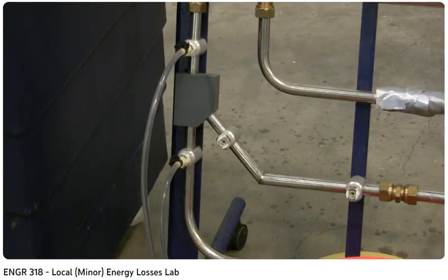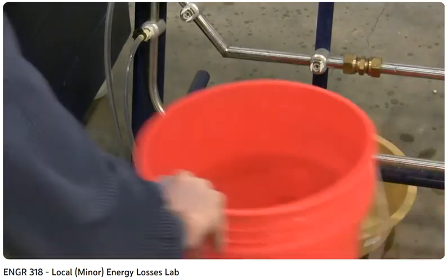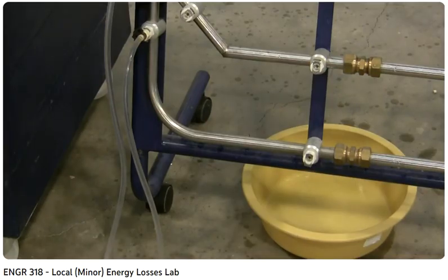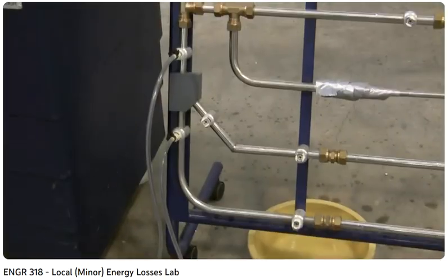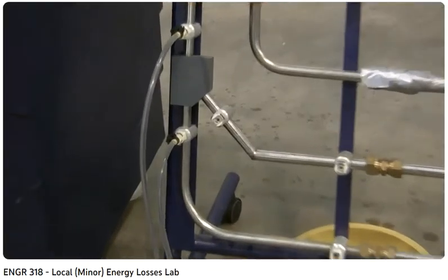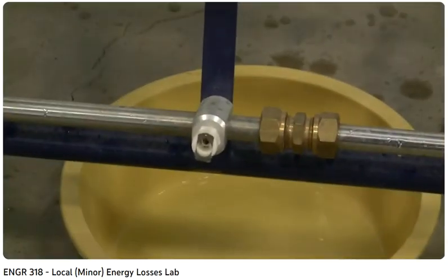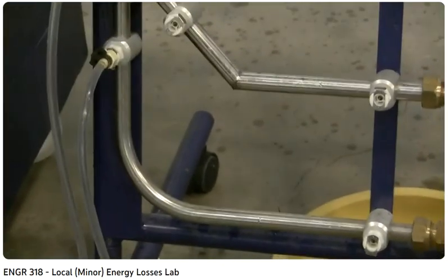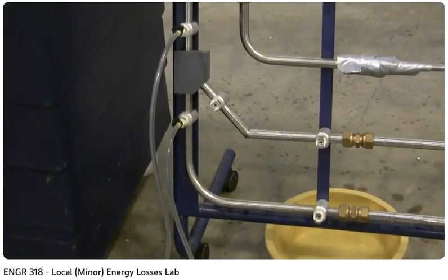Next we're going to move to the long radius 90-degree bend. Rather than unplugging the tap that I've already got in at the lower position, I'm just going to unplug the upper one that's here and move it to this location. Now, swapping what's the upstream and the downstream is going to mean that I'm going to have positive pressures now instead of negative, but that's okay. We still know it's a pressure drop. Let me go ahead and do that.